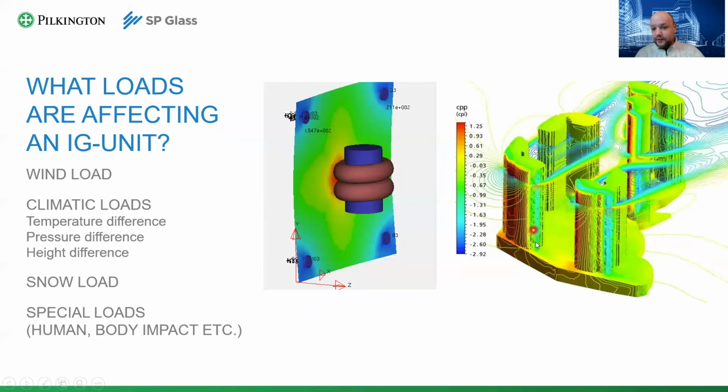You see all of the buildings have corners. And around the corners, you may be seeing these blue zones. These blue zones are areas with negative wind pressure. If the wind is blowing around the corner and suddenly the force increases, the wind stream takes air from neighboring areas and you get a negative load. So, suction. And it can tear your glass away from a facade. These types of loads are usually very high. They are the highest. And they are very interesting because they have a very short duration, 1 to 3 seconds. So keep in mind that peak wind loads have a short duration.